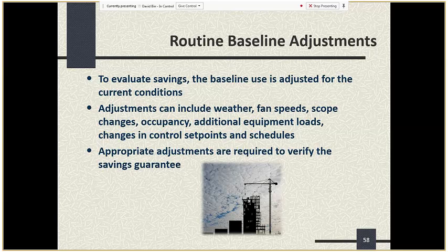I think initially JCI had put forward some proposed set points, but actually as we've been monitoring them through construction years 1 and 2, those set points are rarely achieved, and so JCI basically has just forfeited the idea of trying to get savings from different set points, because the amount of savings is actually quite small to begin with. And so I don't think you're even bothering to take an adjustment. You just basically said, well, we're not going to count savings from set point management for these very small HVAC systems because it's not really worth it.